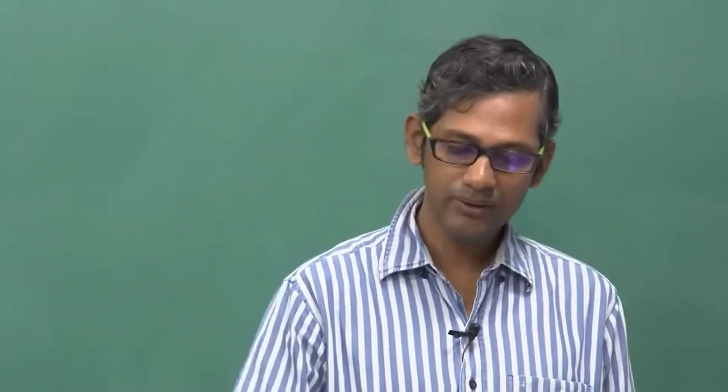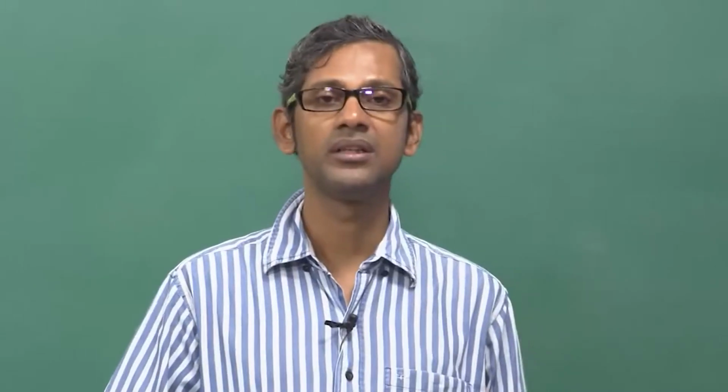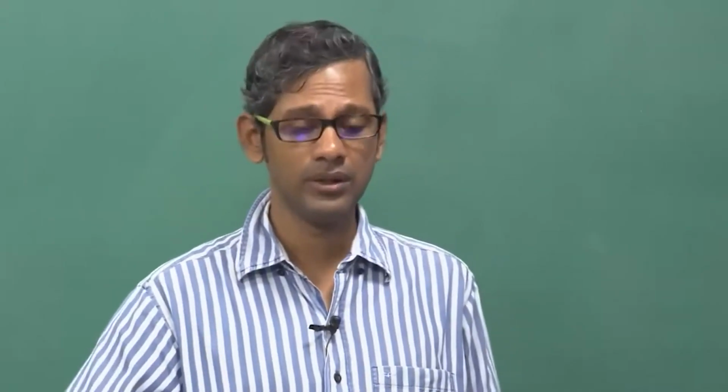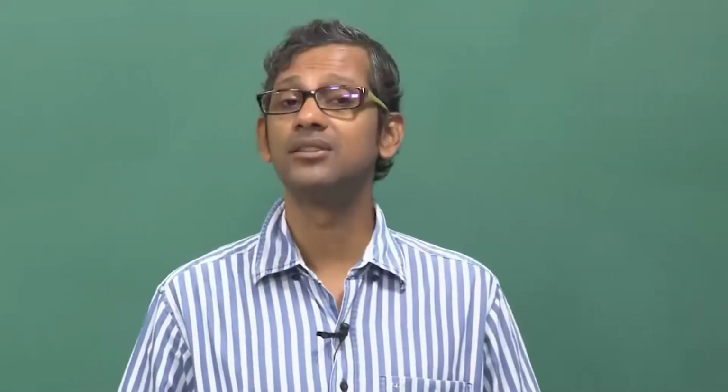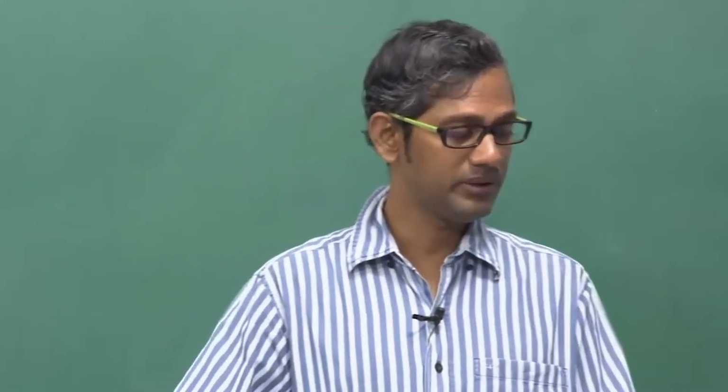one by lattice diffusion. How? Through the lattice, through the bulk of the phase, the partitioning of the solute, which is basically done by diffusion, can happen. Or it can happen along the grain boundaries, things can actually diffuse on the grain boundaries. But the studies which were done very nicely, which I will discuss in the next class in detail, showed that it is not the lattice diffusion, rather it is the diffusion along the grain boundaries which plays the governing role.